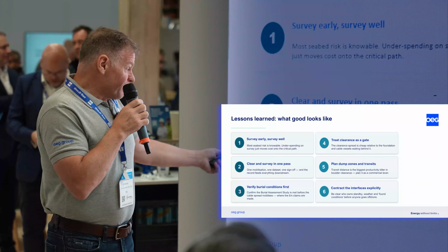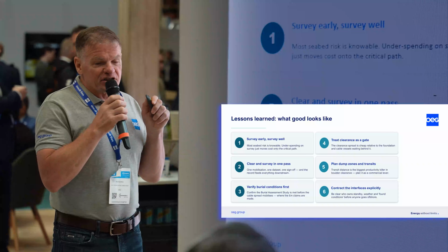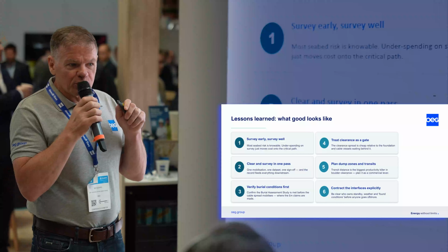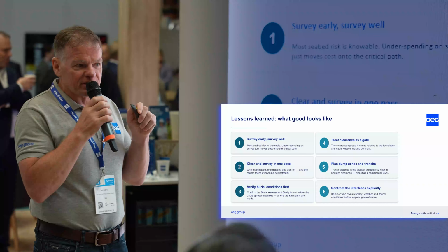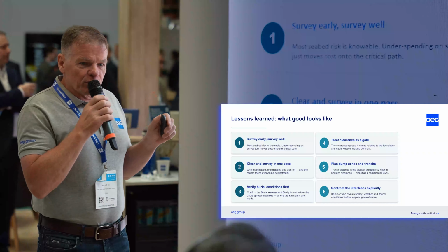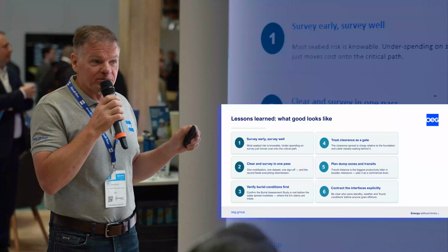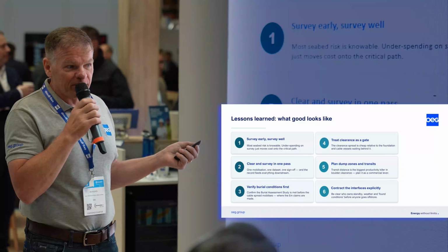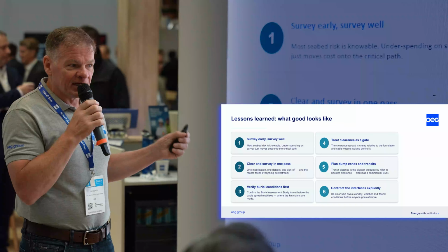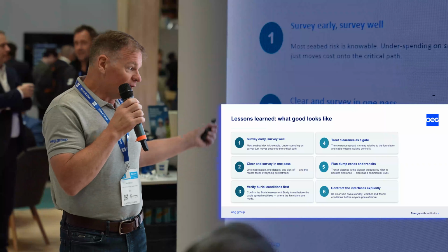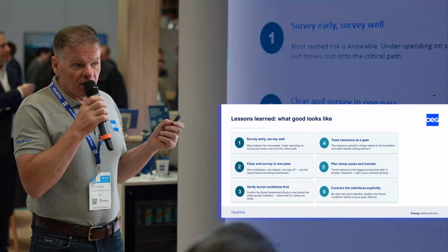We can verify the burial conditions. For some of the UXO, the density of the sands and sediment, and the tidal areas that we go to work in, for UXO especially, not so much boulders in this case, the density of the soil says how quickly we can debury that particular target. Some days it can take 5 days to actually debury a target, because due to the tidal range and the fine sediment of the sand, it reburies and sets like concrete again, and that target's buried again. So we can only work during the slack periods of the tide.